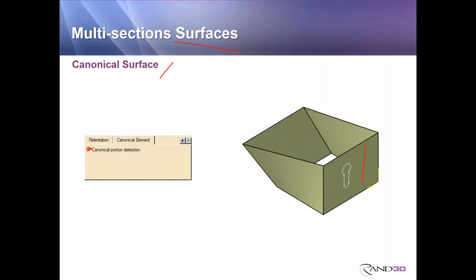Now, if this is not turned on, even though this is flat, the computer would not let you put a sketch on here when you were done. So that's really what that does. It turns these flat faces into planes that CATIA will recognize you can create sketches upon. But again, it's only for surfaces. It doesn't apply for solids. So that's where it gets a little bit confusing.